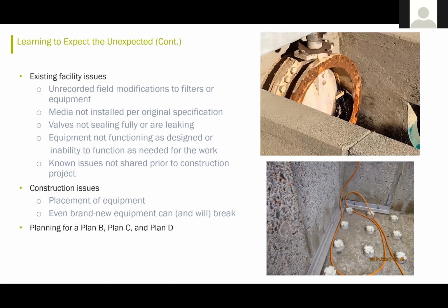Some of the issues related to the existing facility: there had been some unrecorded field modifications of filters and equipment. As indicated earlier, the media was not installed according to the original specification. One of the butterfly valves did not seal, which allowed water into the filters.